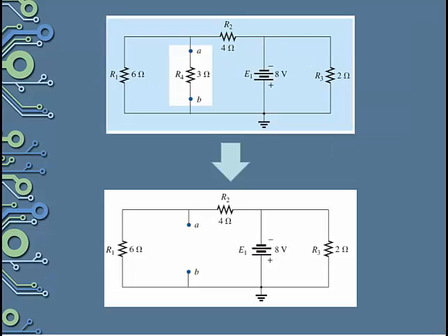The first step in finding the Thevenin equivalent circuit is to remove the portion of the network where the Thevenin equivalent will be found. This is generally depicted as the component or components between the points A and B. In this example, the area left unshaded, that is the 3 ohm resistor, R4, is to be removed and left open for future analysis.